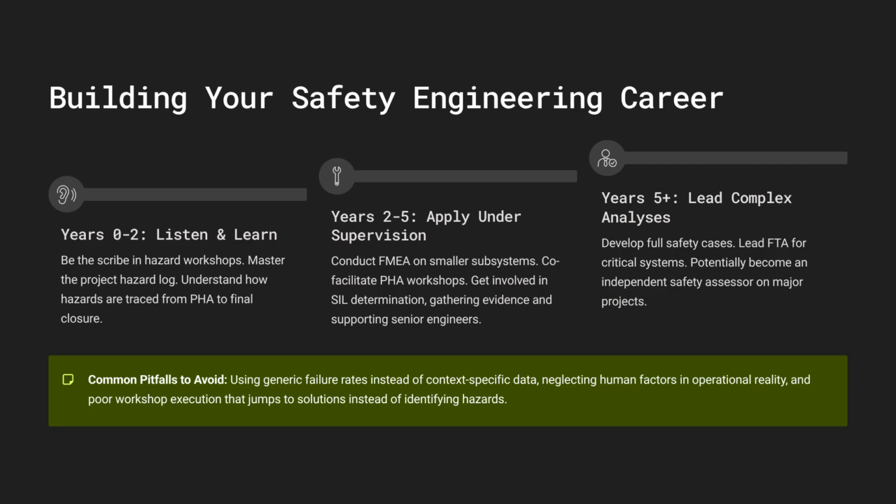So just to wrap up our deep dive today, remember, railway safety isn't ad hoc. It's a systematic life cycle driven by standards. You start broad with preliminary hazard analysis, identifying the potential risks early on. Then system hazard analysis drills into the specific design details, forcing that critical SFARP assessment. And within that framework, we have our key analytical tools: FMECA, the bottom-up detective, looking forward from component failure modes; HAZOP, the structured brainstorm, exploring deviations from design intent using guide words; and FTA, the top-down investigator, working backward from major accidents using logic gates to find vulnerabilities and verify redundancy, all benchmarked against demanding safety integrity levels.